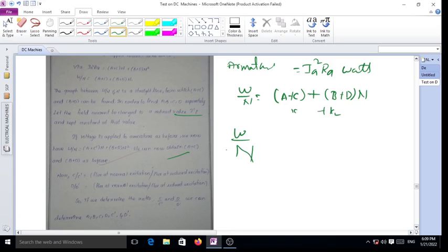That is, we are taking the full excitation and half of the excitation, and asking how much flux there is. So C by C dash is equal to 0.5 by 0.35, and D and D dash are the same for normal excitation.